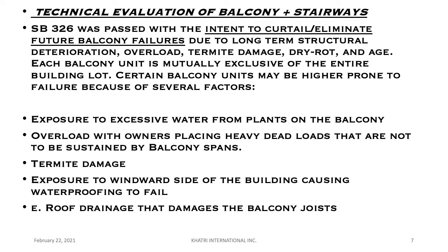And the reason that that's the case is because certain balconies may be more prone to failure because of several factors. One is exposure to excessive water. Maybe some balcony owners are putting potted plants on their balconies and other balcony owners are not. And if you don't inspect the ones with the plants as well as the ones that are not, you're not going to get the full spectrum of damage or no damage. Some owners overload their balconies. They put heavy loads. I've seen them with refrigerators, air conditioning units. I've seen even balconies that are being used as living space, and they're not designed for that.